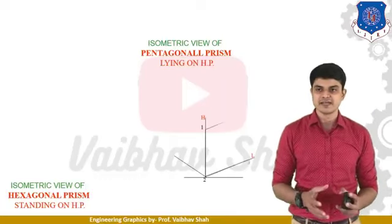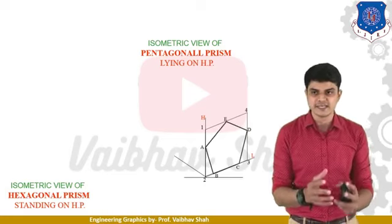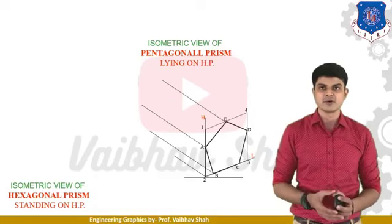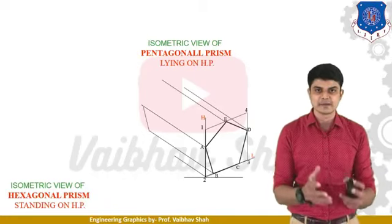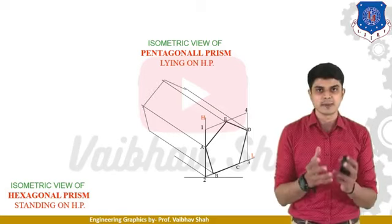First of all, we construct the box on which we will construct the pentagon, as you can see. Then after, we need to draw horizontal lines from each and every point of the pentagon. After constructing these horizontal lines, we need to join the end points of these lines by simple lines, and you will have this pentagonal prism generated, which is resting on HP.